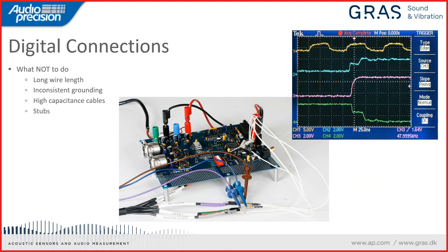And finally, don't leave dangling cables, right? Don't connect a cable to the DUT, and because you're not using that interface, just leave the cable flapping in the wind. These are all things that will impair your physical setup and may result in things just not working.